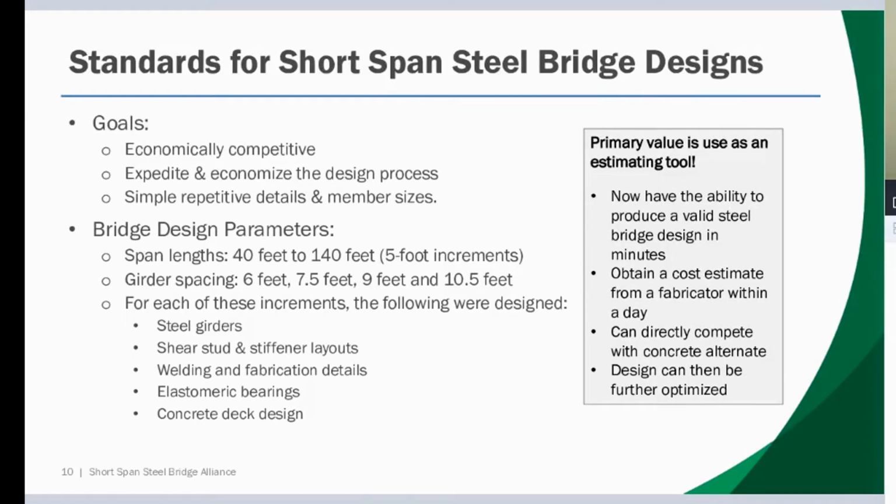So that included the design of the girders and looking at cambers and what have you. We laid out the shear studs, laid out the stiffeners if needed. We provide all of the welding details, the fabrication details. For each of those options, we have an elastomeric bearing that's designed. We have a sample concrete deck design reinforcement laid out. The idea is to provide you as the owner or the consultant with as much information as you can to begin that process. See, the primary value in these standards is really to use as an estimating tool.